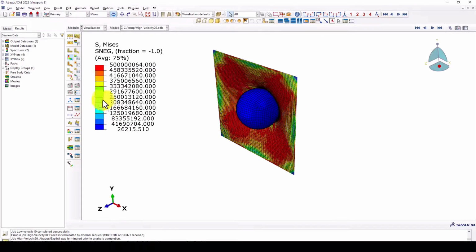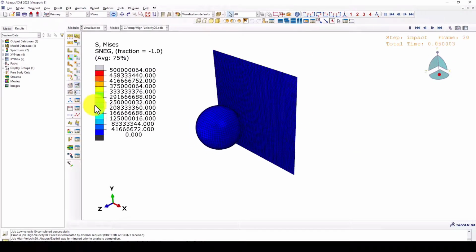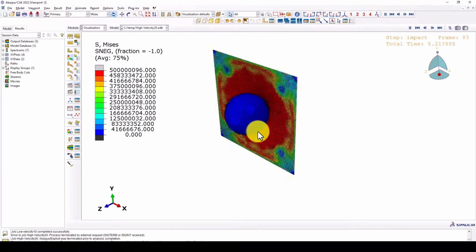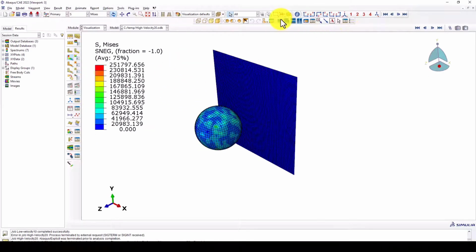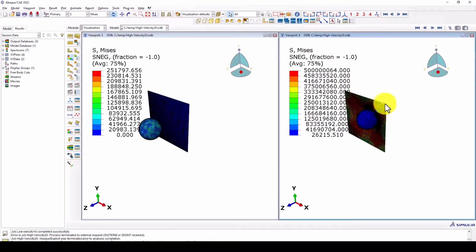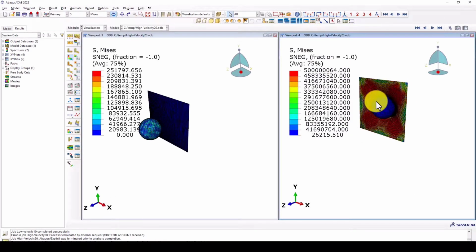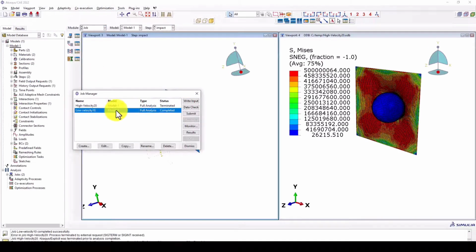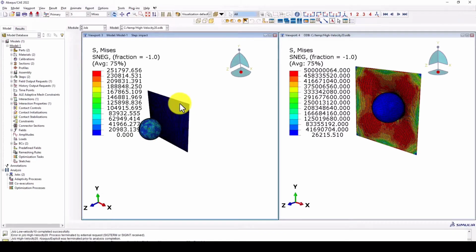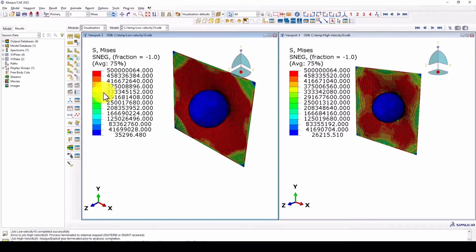Now let me give you a brief about stress transformation equations that is used to define the normal and shear stress on a plane inclined at the angle theta related to the original coordinate axis. We know sigma x equal to normal stress in x direction, sigma y, that is normal stress in y, tau xy, that is shear stress, theta, that is the angle of plane between x-axis, and we know that there are multiple equations for governing the normal stress.